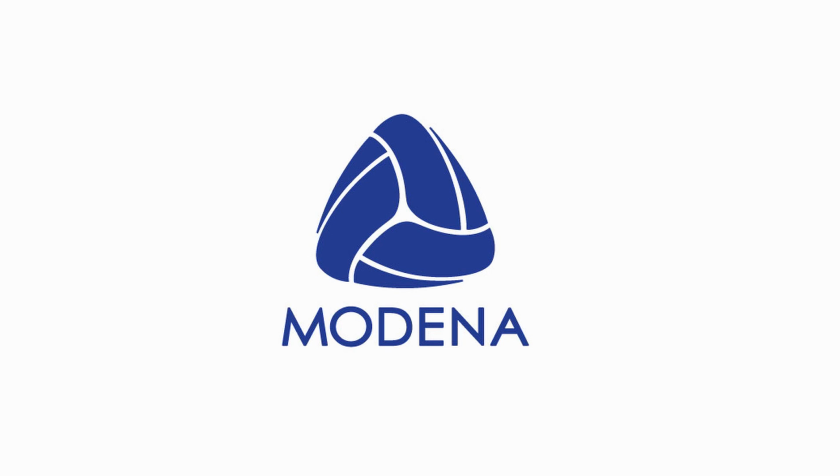Okay, yes. To answer the next question, with initial setup of buildings, when you set out parking, for example, do you add a margin for structure to individual bay sizes? Or is there a way to indicate it? If I'm understanding this question correctly, for the set out, yes, you'd use the snap tools to determine how far away from the building you'd want the parking to start. And then you'd use that tool to further put in the dimensions of the parking. Once you've created the overall parking, you then use Forma to auto-generate the bays and so on.